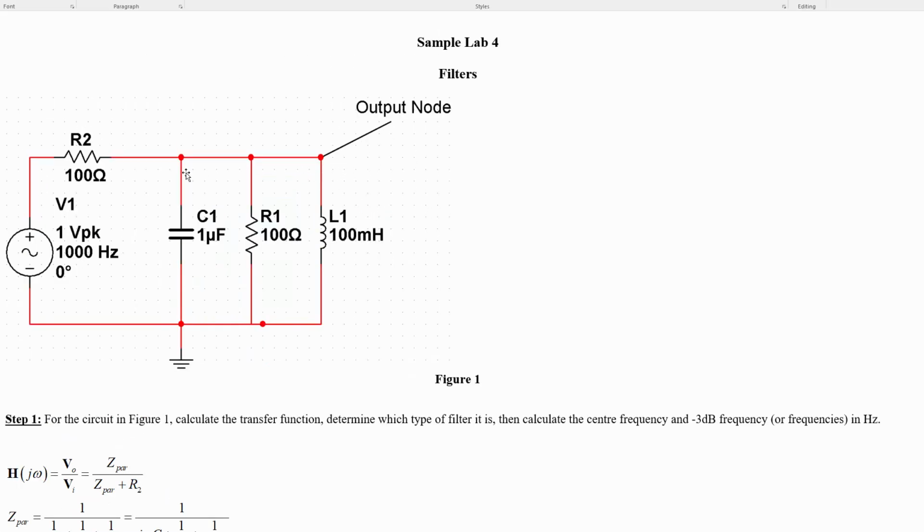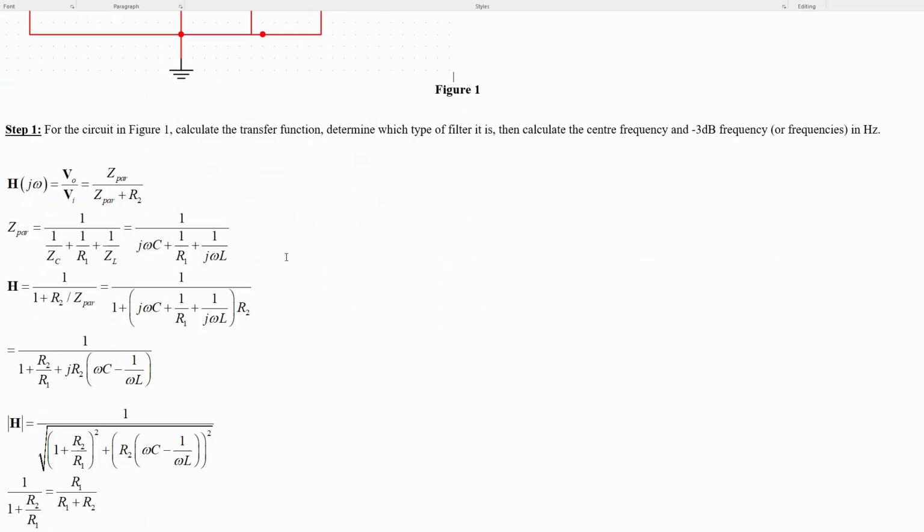When we're at really low frequencies, the inductor is dominating things. And that's where we end up with the positive 90 degrees for the voltage relative to the voltage of the input. And that kind of makes sense because the voltage here versus there is going to be determined by the current, and the voltage in the inductor has to lead the current through it, and vice versa for the capacitor, which explains what's going on at those high frequency points.